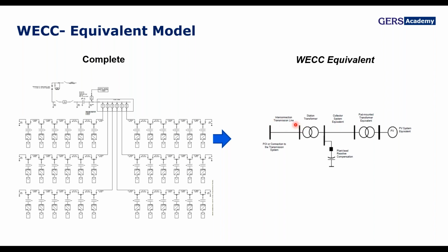Some of the common mistakes that we have at least perceived is that some models don't include the transmission line as irrelevant. I mean, the whole model by itself is very relevant, and it actually doesn't allow generic values. The idea is to have the final configuration that will be implemented on the system. So the parameters that you will use here, even during the planning stage, are the real ones that will appear on the system. This will have a big impact during the transient stage, since the idea is to capture an accurate voltage value at the POI, at the point of interconnection.